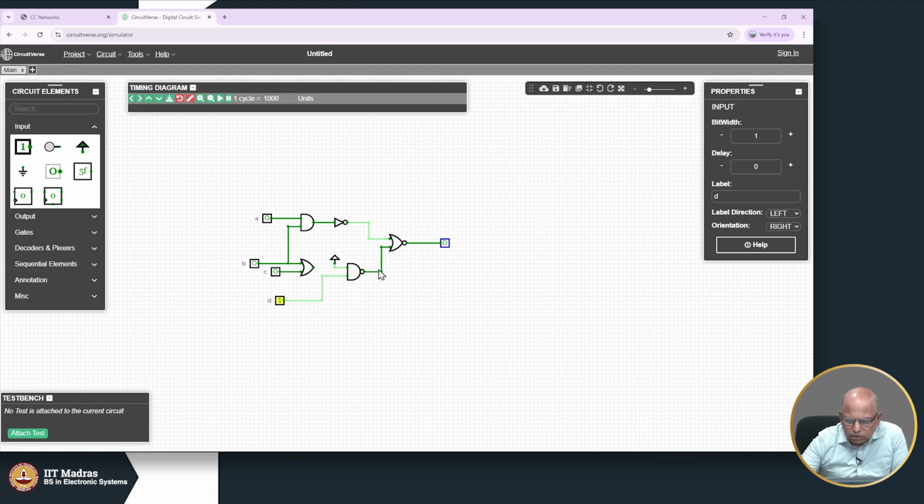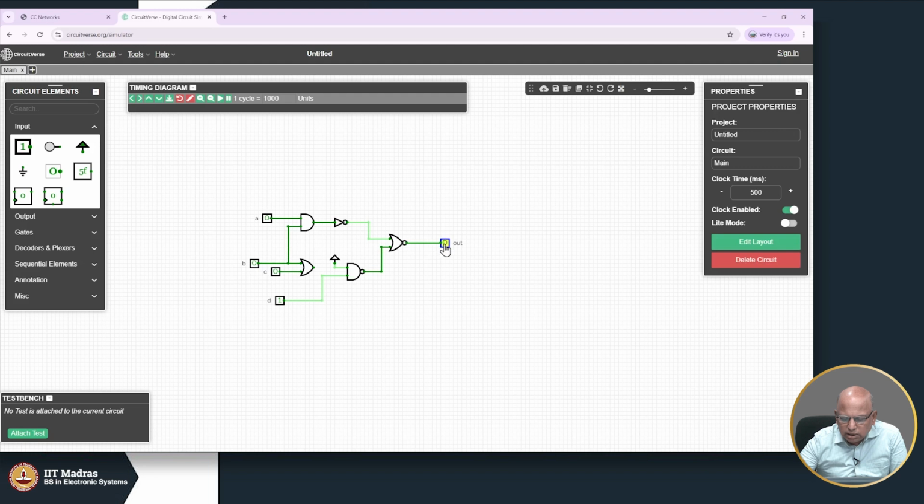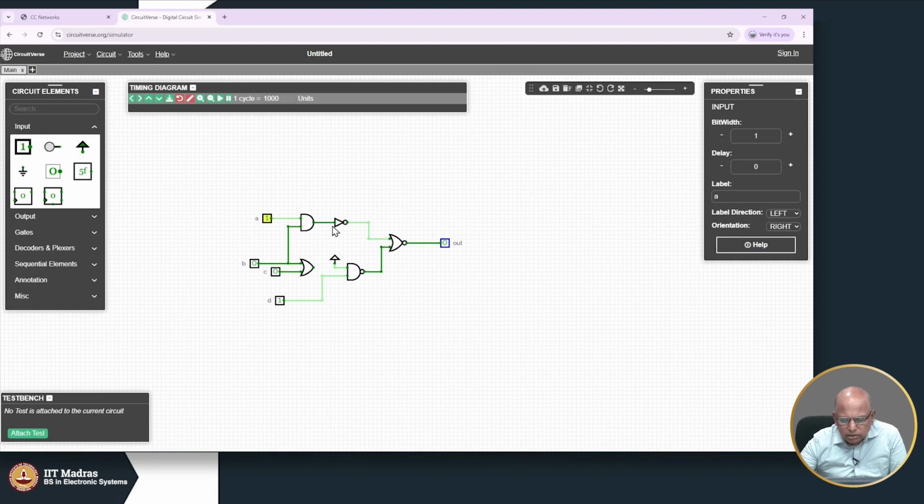So earlier the output here was 1, but now the output here is 0. Okay. But unfortunately, the fault is not propagating to this wire, the output. Okay. We can call the output also as out or something like that. The output is still containing 0. So we have to somehow propagate the fault. It is now propagated up to this point, but in order to propagate it further, we have to put a 0 here. For that reason, we have to put a 1 here. Okay. So now 1 and 0.